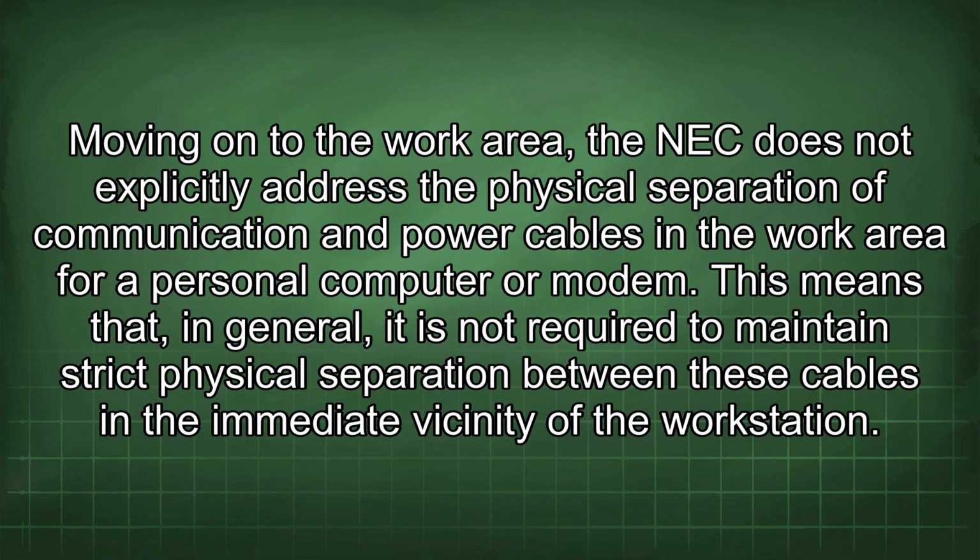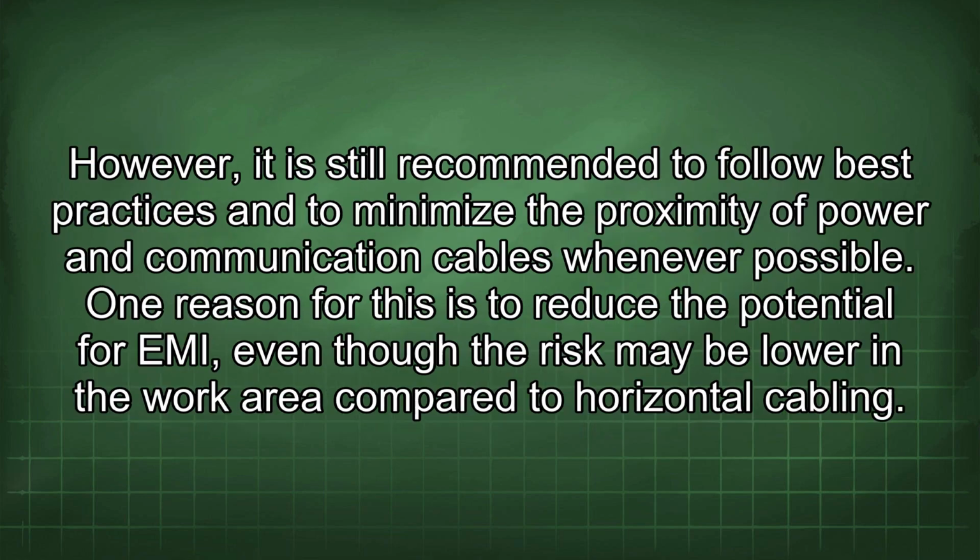Moving on to the work area, the NEC does not explicitly address the physical separation of communication and power cables in the work area for a personal computer or modem. This means that, in general, it is not required to maintain strict physical separation between these cables in the immediate vicinity of the workstation. However, it is still recommended to follow best practices and to minimize the proximity of power and communication cables whenever possible.